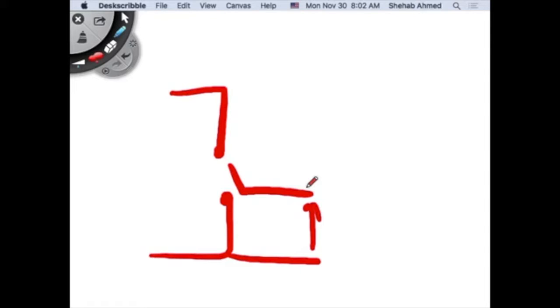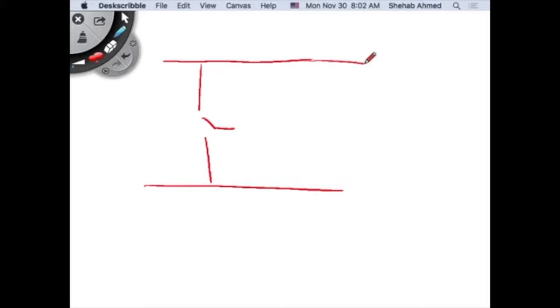It's the same way to derive it, but you may be operating with the complementary duty ratio. So one arm may be operating with a duty ratio of D1, and the other arm may be operating with a ratio of 1 minus D1, or one arm may be operating with D1 and the other arm with D2, right? Because to get the 0 states, meaning this is on top and this is on top, they're not complementary anymore, right? So it's not D1 here and then 1 minus D1. It would be D1 and D2 in that case, right? And we derived both cases.